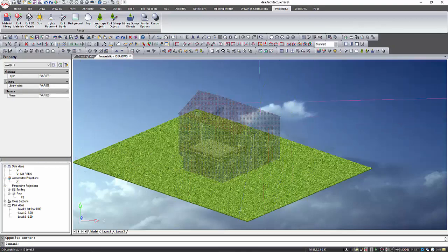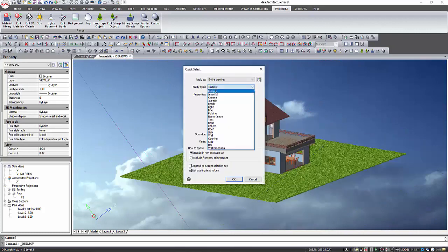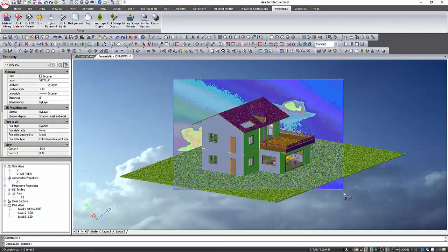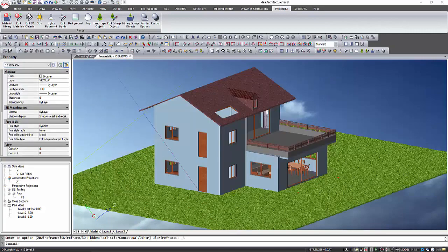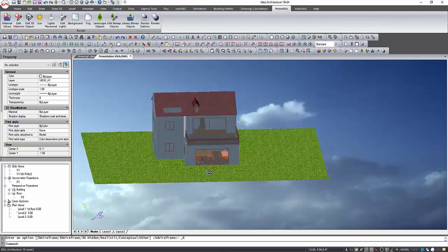Of course, we can do the same for any BIM entity. Let's make a change to the side material of the slabs too. We can use also the command filter if we prefer so. Otherwise, as we did before, from the Properties panel we select the slabs and we make the change. You see how fast you can do any change to the materials of the BIM entities in this way.